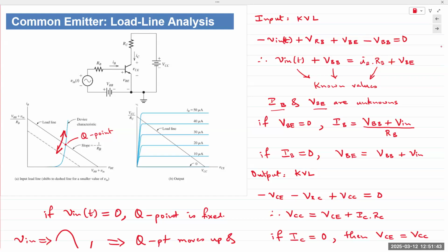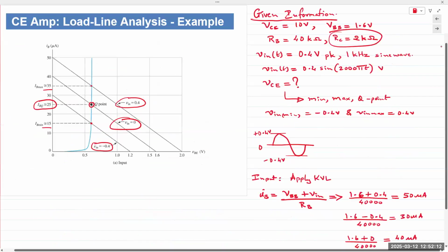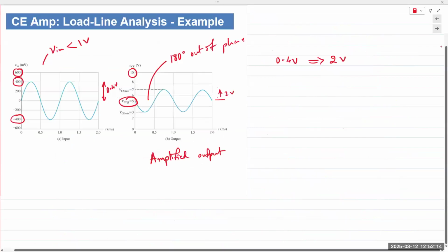Voltage polarities are reversed. VBE in an NPN transistor is 0.7. In a PNP, it would be VEB. So VBE in a PNP would be minus 0.7, or VEB is plus 0.7, right? Same voltage, we're just flipping because of holes and electrons. That's all. So load line analysis, make sure you go through this entire example.